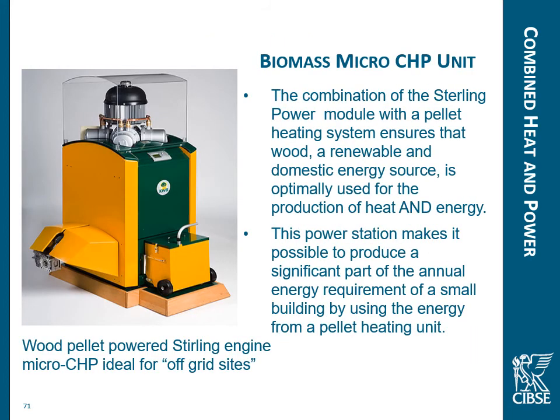Biomass CHPs can work quite well in areas where we've got quite a low demand, a low electric supply capacity. So if we're in an area where the electric supply is not big enough, we can use biomass CHPs. And then in rural areas, we might have a good supply of the actual biomass.